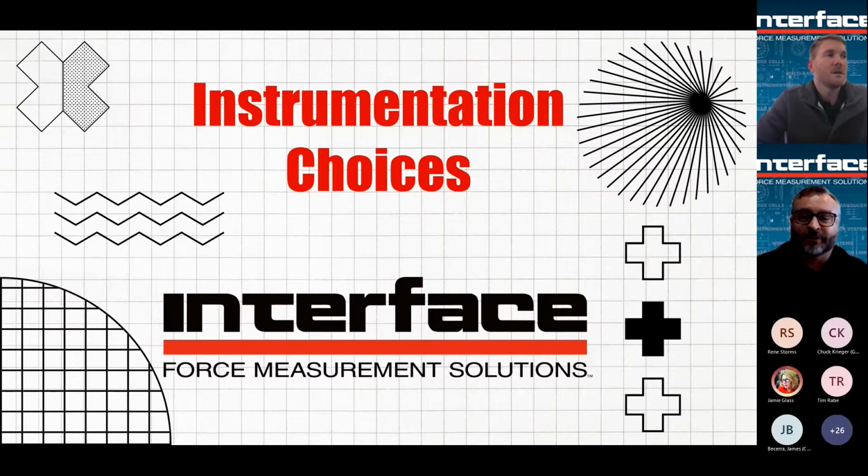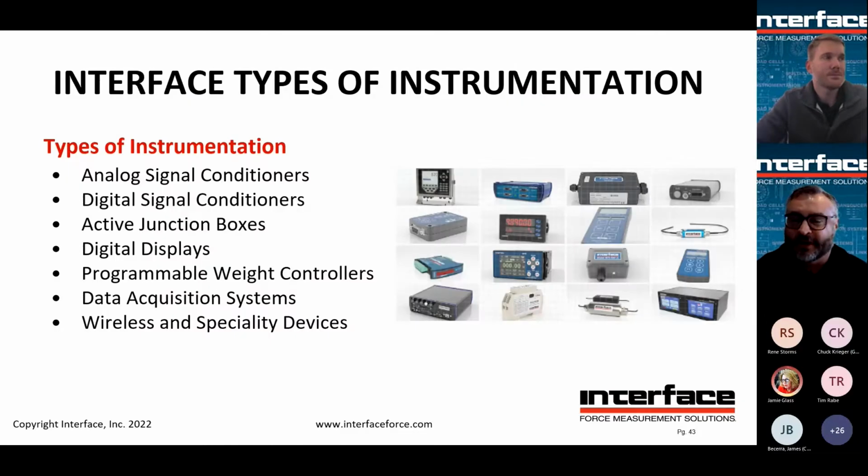All right, instrument choices. All of these things we've been talking about thus far have had load cells in them with millivolts per volt outputs. Obviously that doesn't do any good without something to read that signal. That could be something simple like a display, or very complex like a controller or a data acquisition system managing a complex process. Here are some examples of types of instrumentation commonly used in weighing.